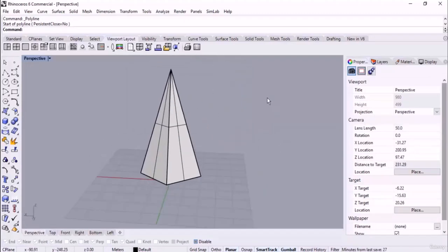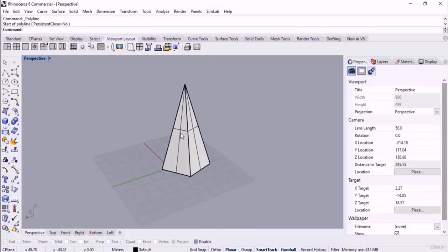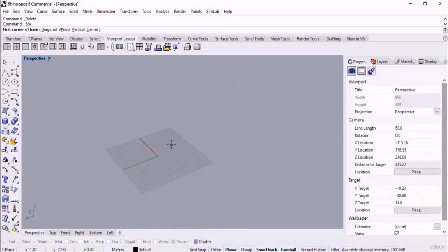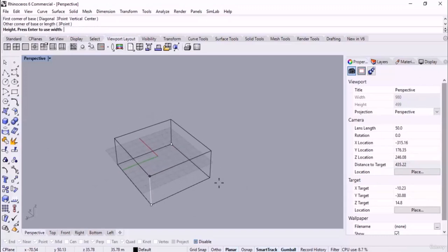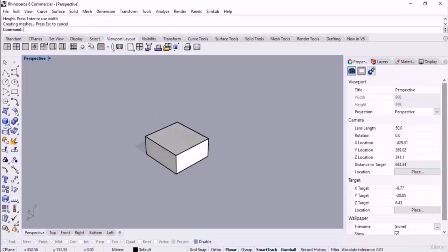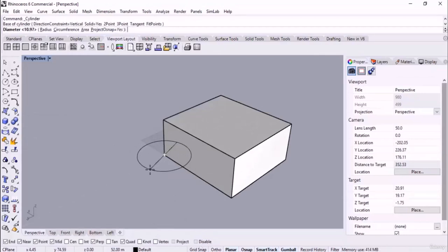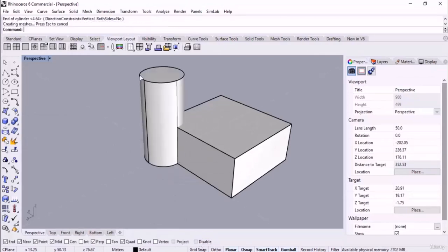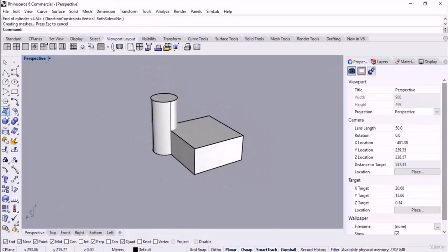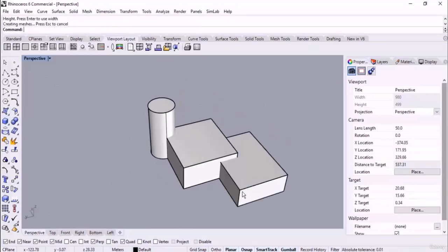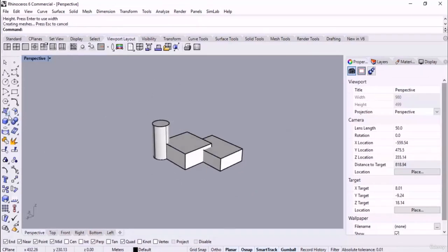But let's talk about the graphical style for displaying the objects in the scene. Here let me place multiple objects in the scene to prepare the example for teaching you the graphical styles. I enable the object snaps. I sketched another object. And one more object here, as you can see.